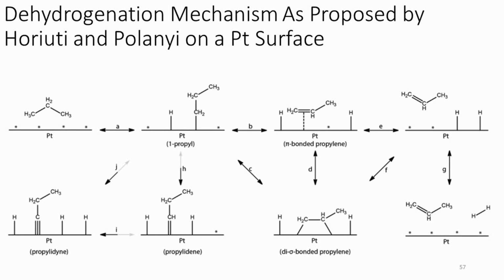This mechanism follows Langmuir-Hinshelwood kinetics, where all of the surface sites of the catalyst are considered to be identical. The Horiuti-Polanyi mechanism consists of four main steps: dissociative adsorption of the paraffin, CH cleavage of a second hydrogen atom, formation of hydrogen molecules, and subsequent desorption of both the hydrogen and the olefin, as shown in the scheme. Both the CH cleavage step and the dissociative adsorption of the paraffin have been suggested as the rate-limiting step of the dehydrogenation reaction.